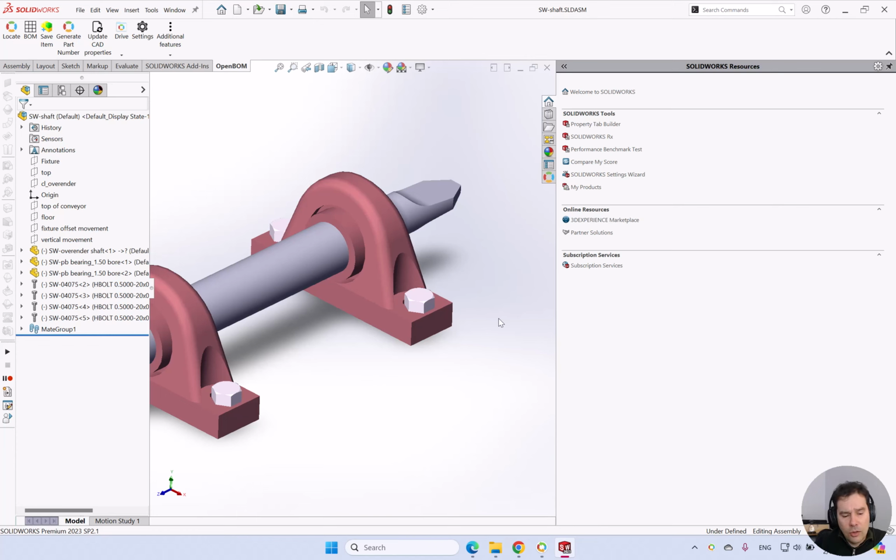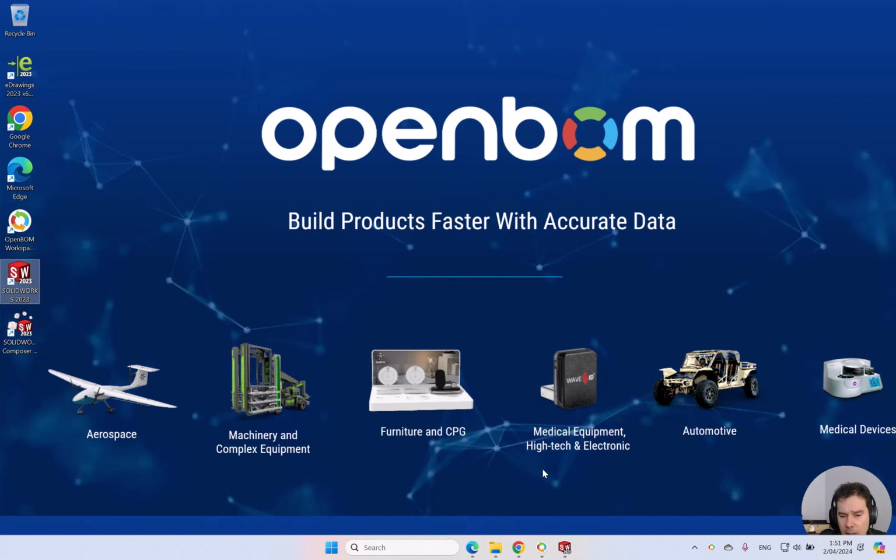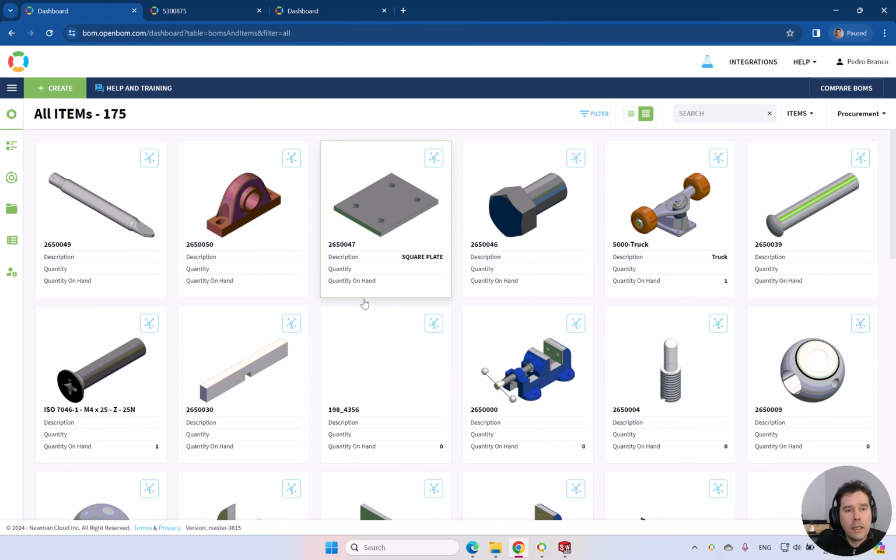So we're going to use two different methods, one more simple and another one more advanced. The simple one is just using a BOM template with that extra property as a BOM instance property. I'll show you how to do that. And then another more advanced one will be bringing this default data from a SolidWorks property coming from the SolidWorks file properties data. So let's start with an example with the BOM property on a BOM template.